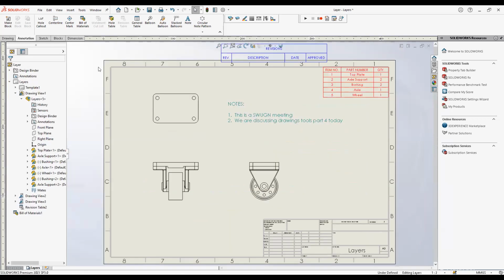So similarly, we can use layers in a very productive way. And there is one more advantage of using layers: a lot of people work with DWG or DXF files, and they want things to be in different layers so that it is easier to read the drawing. So using layers, you can do that. And when you export your files to DWG or DXF formats, layers will be exported and the entities will be kept based on how you have set them on the layers.